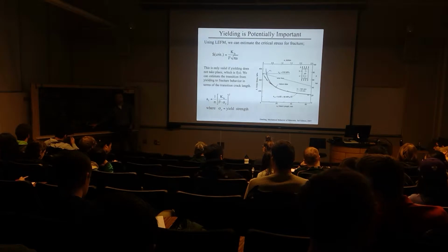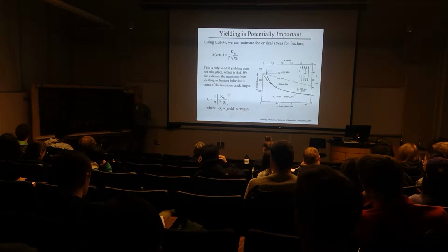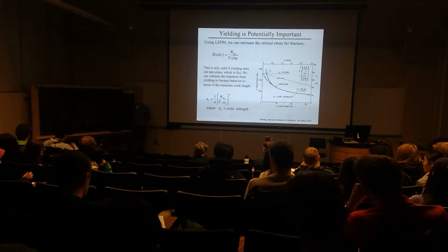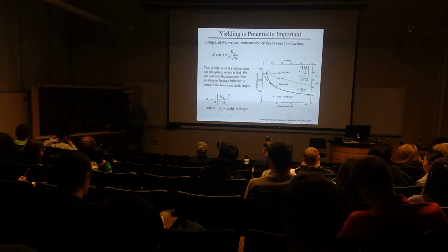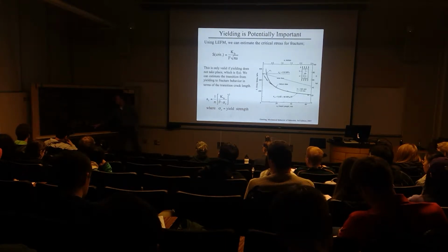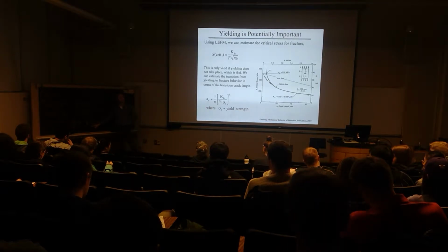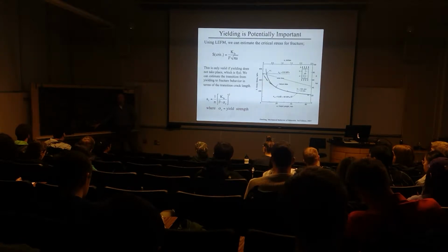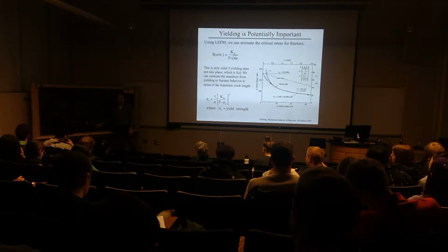What can I do with that knowledge, that information, that data? If I know the fracture toughness of the material, I can estimate what the stress was, the maximum stress in that structure. So I can see, hey, was that load or that stress within the bounds of what we expected to happen in that structure? So I can see if it was overload. Okay? That assumes, again, that this flaw length was greater than the transition flaw length of the material. If it wasn't, then I would say, hey, this shouldn't be a fracture problem.